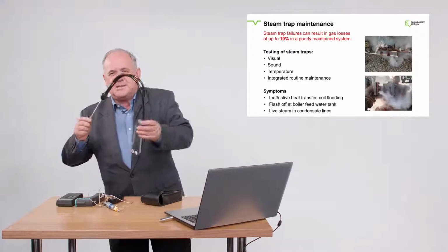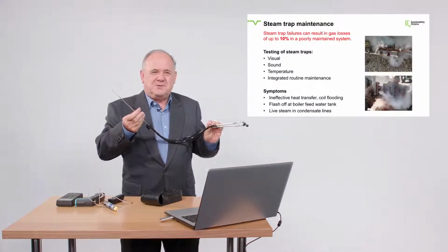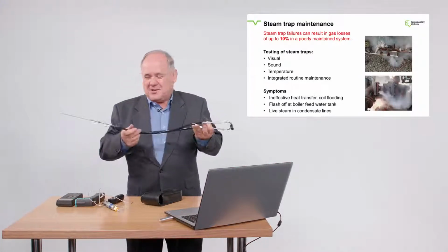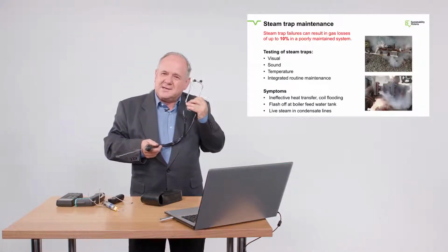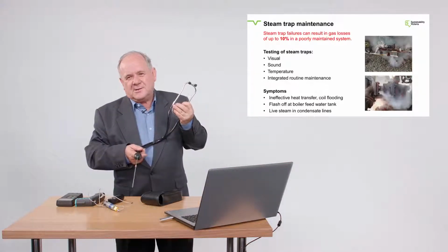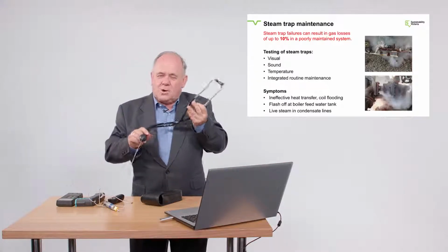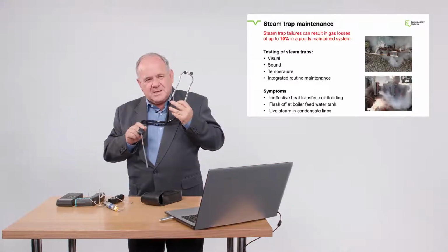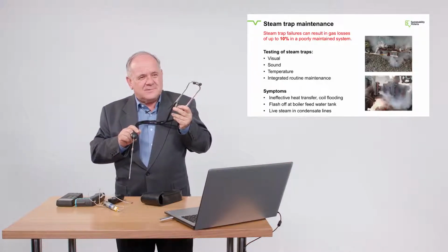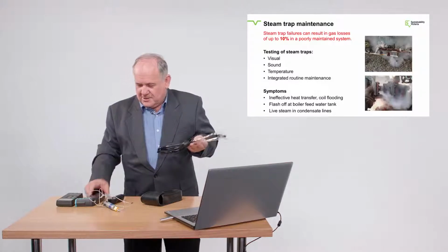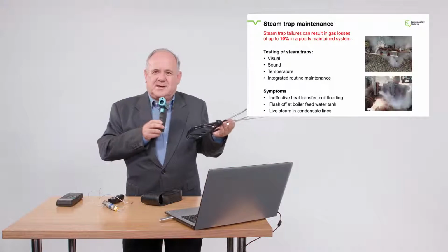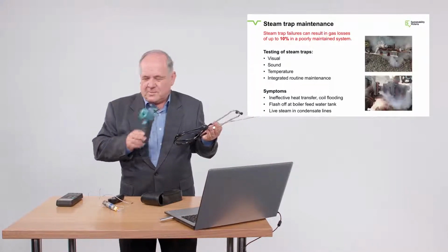This is a mechanic's stethoscope. If you can go to Super Cheap or Autobarn, they're $30. And they're like a doctor's stethoscope, but basically you're listening for the difference between steam passing through the orifice and condensate. So while you'll get the feeling, you can hear the velocity differences and the noise. So that tells you whether the trap's working well or not. So, okay, for the grand investment of $60 or $70, we're out there chasing steam trap leaks.